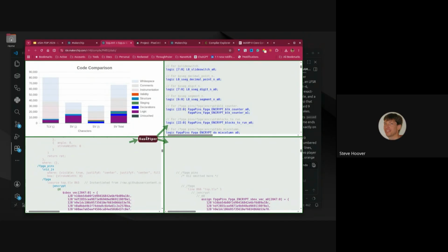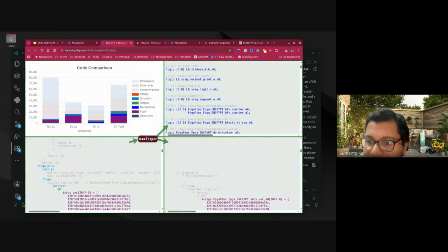Right, and the motivation for the integration is to make this as seamless and incremental as possible for folks to transition from Verilog to TL-Verilog. You can have a Verilog file that's 6,000 lines of code, and then 10 lines of that you want to write in TL-Verilog. You can do that. So it's not exactly a language extension as you might think of language extensions. It's sort of regional. You say, in this region, I want TL-Verilog constructs, but that region can be as small as you want. Any other questions?